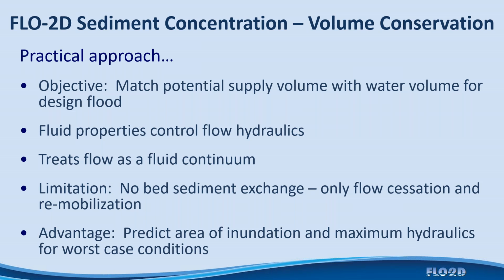So we'll talk about the fluid properties of the mudflow and how the model treats this as a continuum, meaning that there is no exchange of sediment with the bed. The flow only ceases to flow, or it can remobilize, but we're not scouring and depositing out of the flow onto the bed. And I'll talk about that a little bit later with respect to a two-phase flow model that we're starting to work on to put into the model. So the idea is to predict areas of inundation and the maximum hydraulics associated with either clear water flows or mudflows for a worst case scenario, and this will allow you to delineate the hazard.